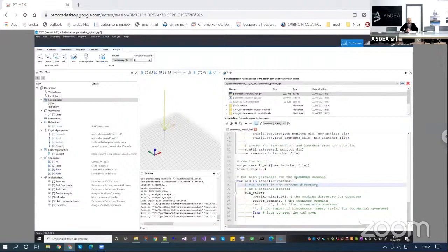So probably it's not so useful to run parametric analysis, but at the same time it can be useful because actually you can run one analysis and wait for the other, because in this case, I knew that the model was small. So I simply performed a loop and I simply ran an OpenSees instance without waiting for it to finish, okay? So I ran all of these instances at the same time.